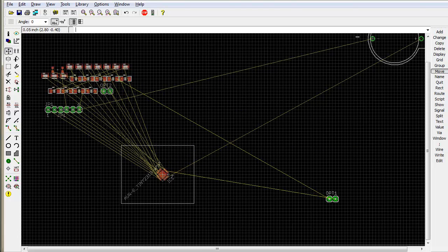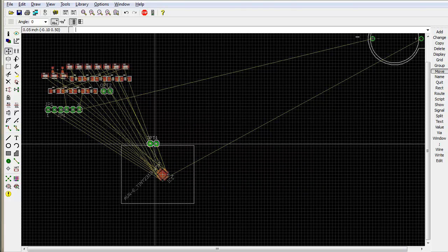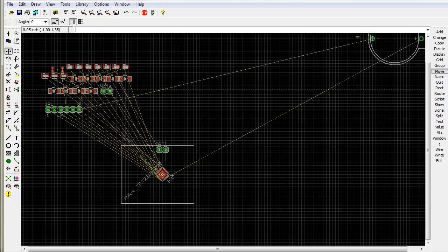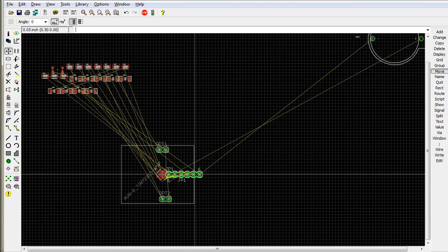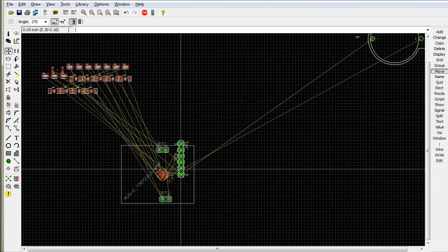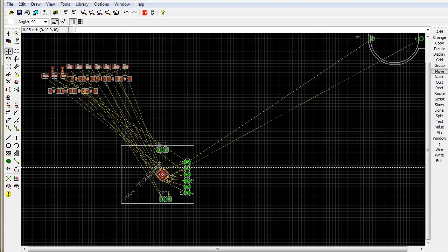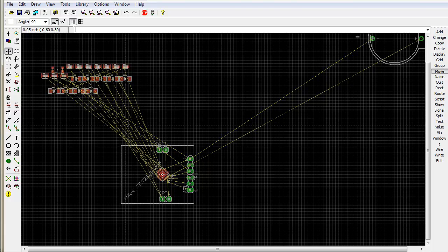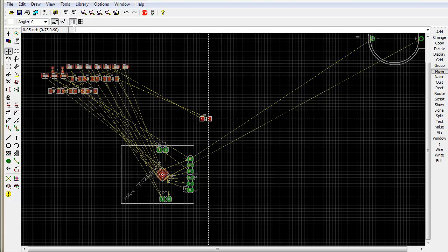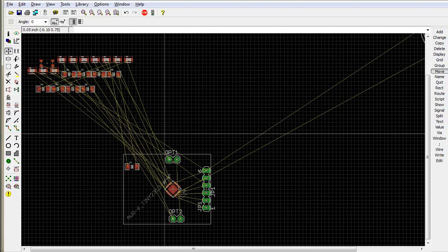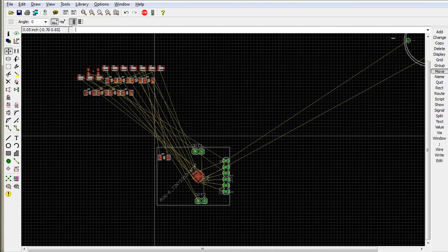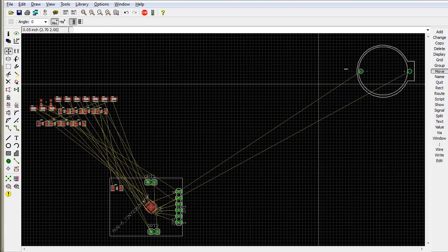We're going to drop opt1 down to the top side, just for the moment. Rough placement is fine. Some of these are going to be upside down. We're going to move this. I'm using the right mouse button to rotate it, clicking on it with the left mouse button. Again, we're doing rough placing here. We can see the components. Now, when you do Alt F2, it tries to get everything in.